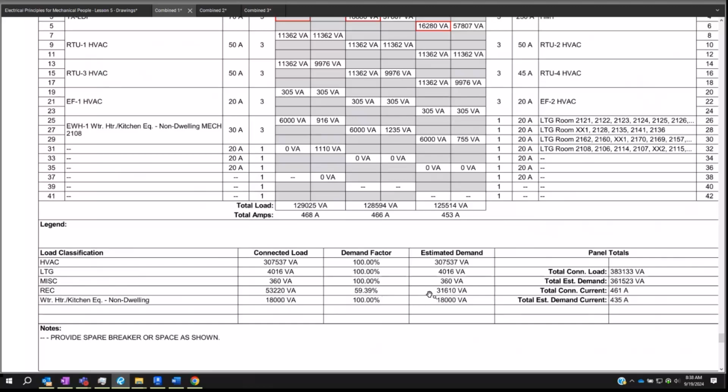The reason is that you're not going to have every single receptacle pulling an amp and a half all the time. That's just not how that works. That's why the NEC fully understands, just derate this. We're swinging for the fences regardless. Just do it like this.